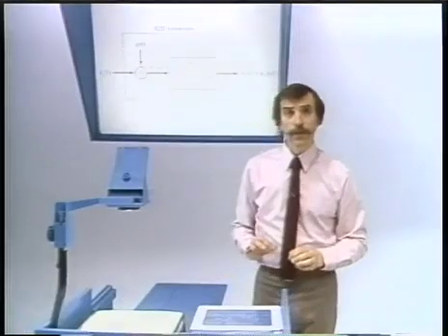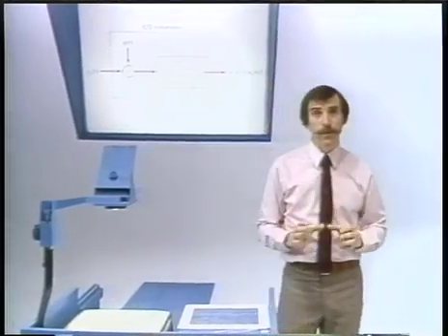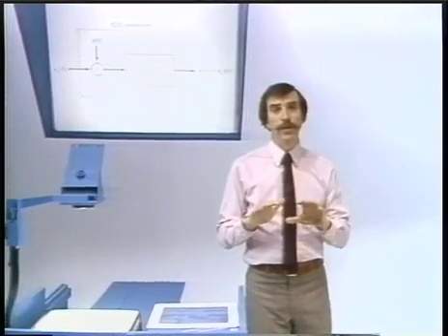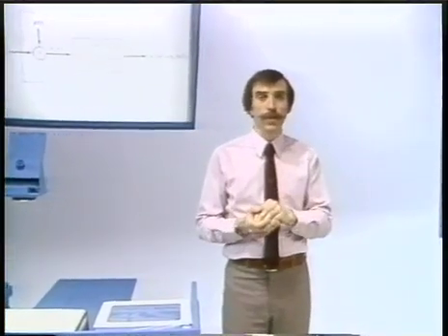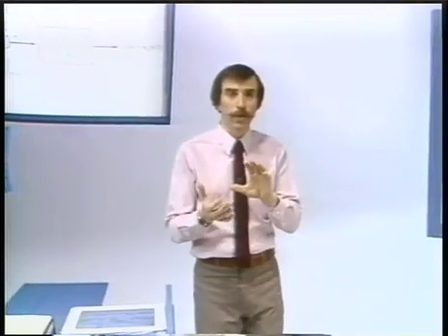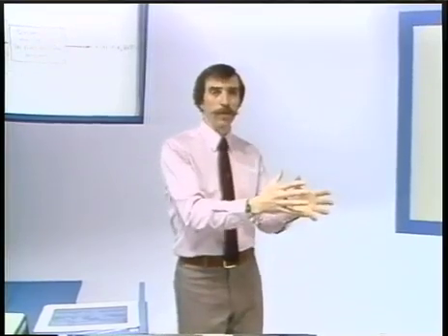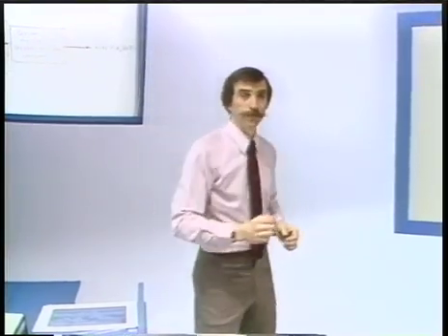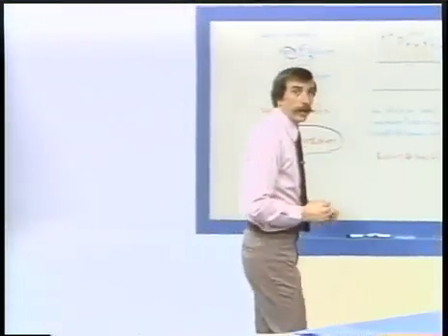So what I'd like to do as a first step in understanding this process is to analyze it, in particular with our attention focused on trying to understand what the relationship is in the frequency domain between the discrete time Fourier transform of the sequence, the discrete time signal, and the continuous time Fourier transform of the original unsampled and then the sampled signal. So let's go through that.